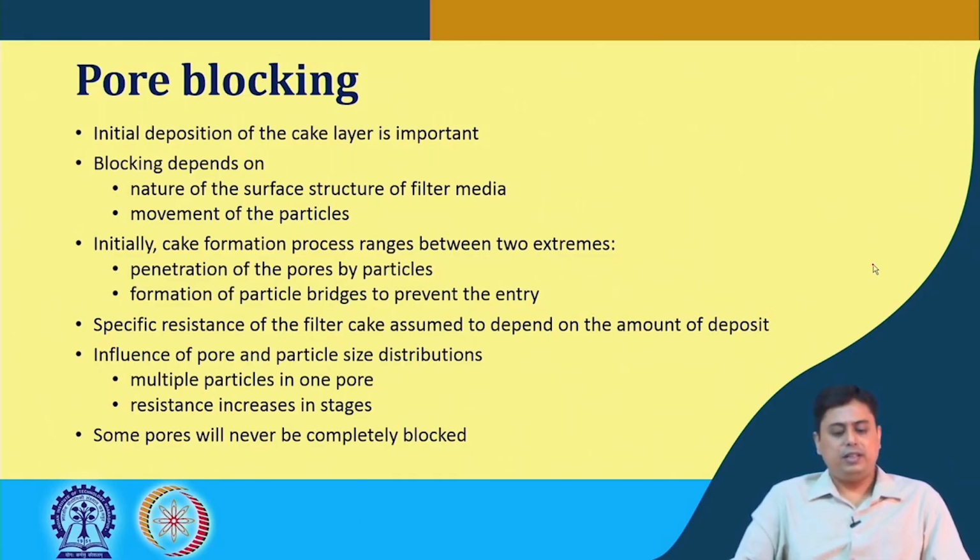Now, the specific resistance of cake is typically assumed to be dependent on the amount of deposit, and this assumption works pretty nicely, because after several experiments it has been proved that this specific resistance of the filter cake is actually dependent on the amount of the deposit on the top of the filter medium.